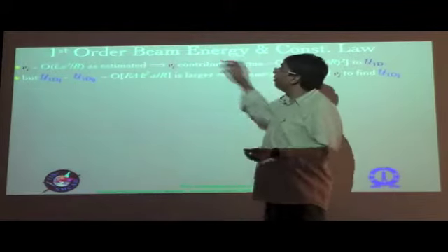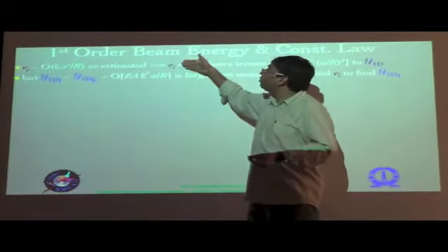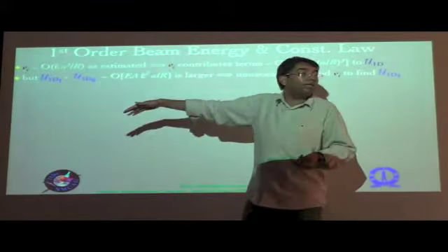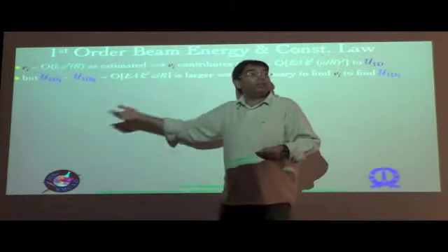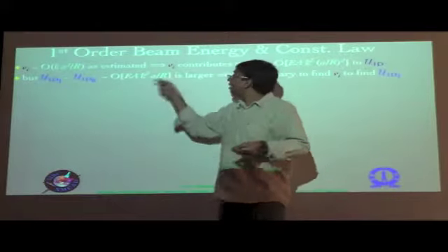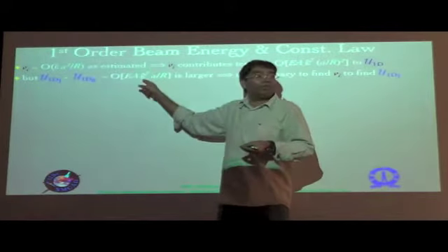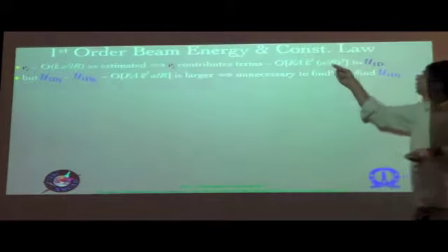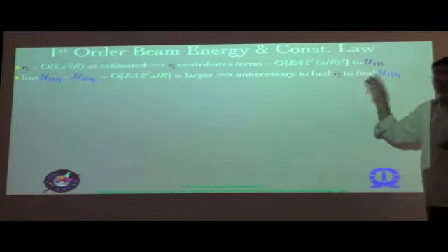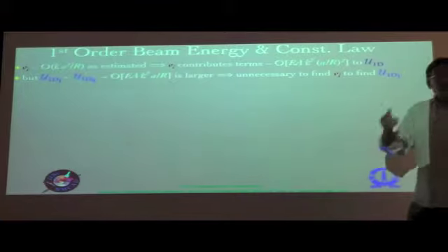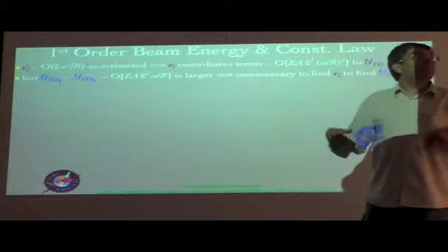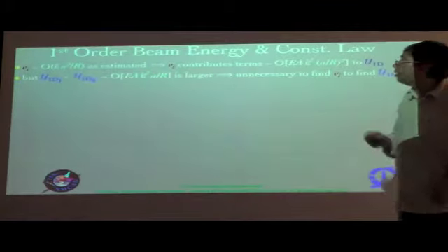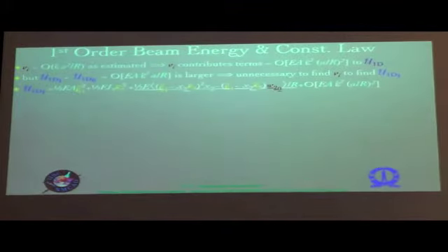Of course, you have a methodology in terms of how to determine Vi and substitute it to get U1D1, but if your interest is to get only the next order of magnitude terms in the energy, they are only A by R times the classical measures, whereas Vi contributes A by R squared times the classical measures. So you don't need Vi to be determined. In other words, you might get the governing differential equations for Vi, but you don't need to solve them in order to get the energy of the next higher order approximation. So it is unnecessary to find Vi to find U1D1.